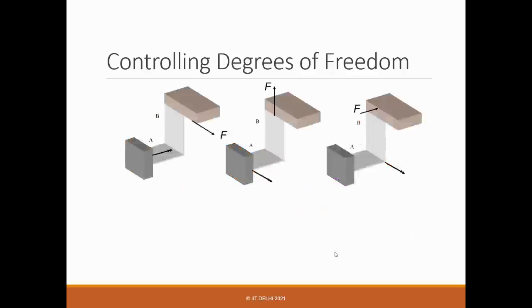So in the case of folded sheet flexure, what you realize is that when you apply force elsewhere, not along the fold line, one of these members, one of the sheet flexures, the folded one, will get distorted because the force is applied somewhere else. It's not lying in the plane. If it's on the plane, it's very stiff. So for instance, it's very easy to demonstrate.